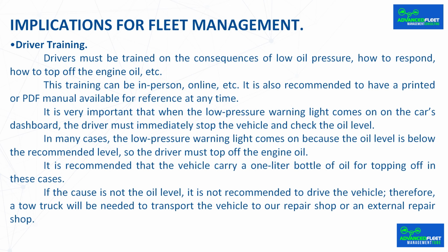In many cases, the low pressure warning light comes on because the oil level is below the recommended level, so the driver must top off the engine oil. It is recommended that the vehicle carry a 1-liter bottle of oil for topping off in these cases. If the cause is not the oil level, it is not recommended to drive the vehicle. Therefore, a tow truck will be needed to transport the vehicle to our repair shop or an external repair shop.